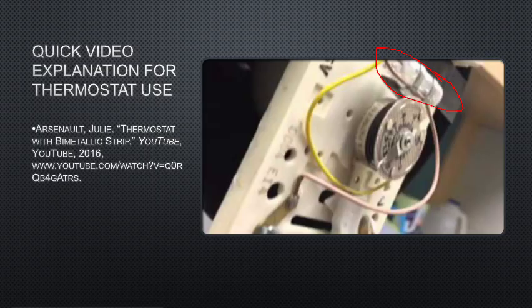But in this little bulb that I have circled, when you turn the heater on, this coil, this apparatus, would turn over, and there's a little mercury in this bulb that would float down to here and attach these two cords, which would then turn on the heater. And then as the temperature rises, this coil would kind of unravel until the mercury came back to a settled position in the top, and then the connection between these two wires would no longer be there because the mercury moved, and then your heater would turn off. So that's kind of how we could see it used in one application.